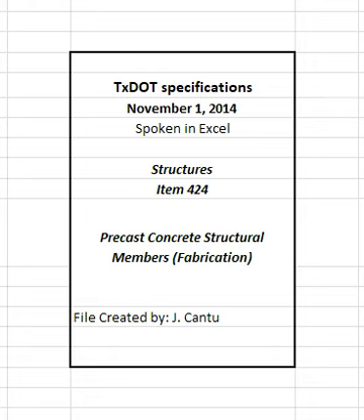Submit for approval any other moisture barrier systems for protecting strands. Before shipment of members, remove concrete, paste, dirt, oil, or other bond-breaking substances from exposed reinforcing steel, and remove laitance, dirt, oil, or other bond-breaking substances from concrete surfaces to be in contact with cast-in-place concrete.